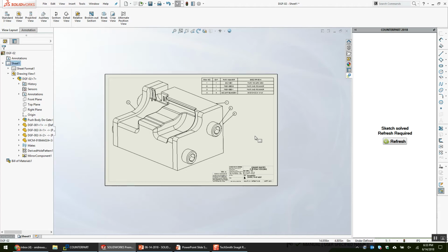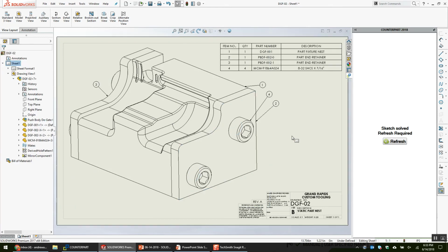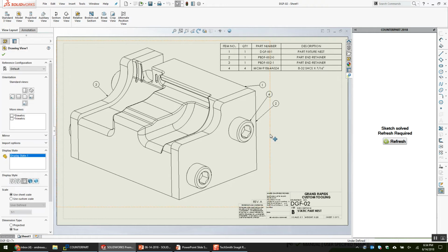So the envelope is a good option for that. I just don't like envelopes because I don't like the transparency of it, and it's irritating to look at, so I'm just not in the habit of using that. But if I did use it, my drawing would have been easier. I usually make a configuration that doesn't show the parts. Yep, that would work. If you do suppress it, then sometimes I used a bunch of external references here to... I don't suppress it, I just hide it. Configuration. Oh, hidden. Yeah, you could also do that with display states.